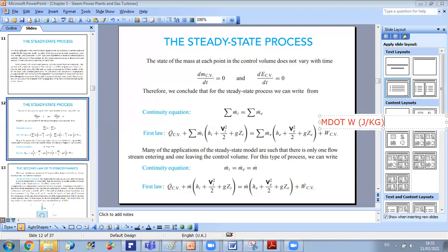So what I will do first, I will write this equation for the compressor, and I will find the value of m dot. And once I find the mass flow rate, I will use it after to find the heat rate in the exchanger. So here, if we apply this equation for our compressor, first, as we said, if they don't mention anything, in general, the compressor is well insulated, so no heat rate.